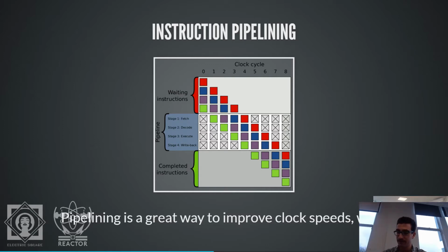we want to be able to achieve much faster clock cycles because we want computers to run faster. And one of the ways to get a faster clock cycle is to reduce the amount of work a CPU has to do in a given clock cycle. Whereas, ages ago, the instruction for grabbing the contents of a piece of memory, loading it onto the CPU, performing an operation on it, and then putting it back into memory, would have been done in a single clock cycle, right? But that's a lot of work to do in that amount of time.